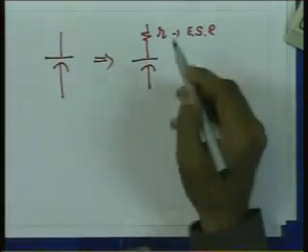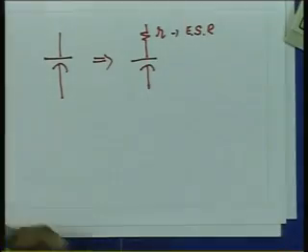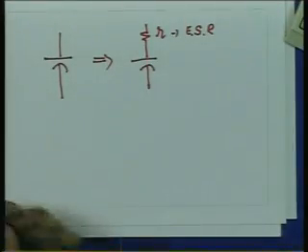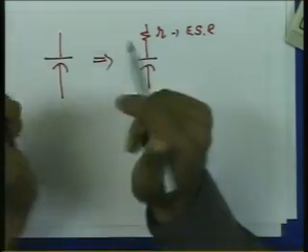For this case we will represent a small resistor in series with an ideal capacitor. This ESR, or effective resistance, represents the dielectric loss, the contact resistance and other losses. And we all know that dielectric material is a very poor conductor of heat.